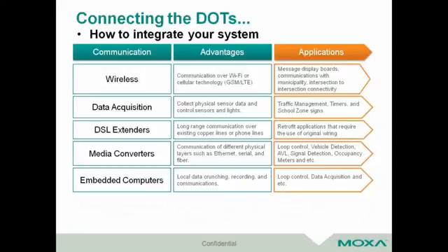But there's also bridging or transparent firewalls that you can input in your system to prevent communications. Let's say, for example, you have devices out on the field, controllers that use Modbus or some sort of protocol. You can have the bridge transparency to filter out specific protocols so they don't get pushed up on your Ethernet backbone, or you don't have someone writing into your device and making changes because someone at the central location doesn't know what he's doing. You can filter this using that, and that's what I mean.